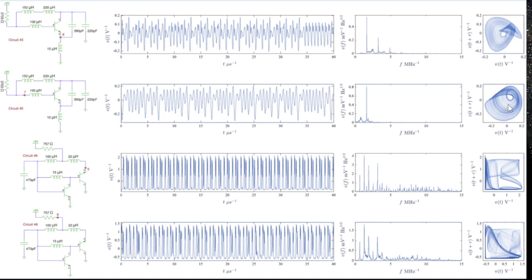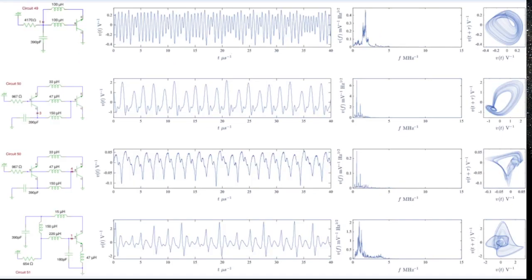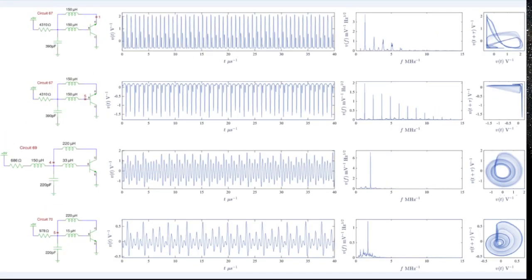But anyway, if you look over on the right at that second picture, you can see the variation between the big loop and the small loop. And all that stuff in between is like what we saw as we were adjusting a value in that feedback, and it was oscillating back and forth. Now, what they're showing here in that second diagram with the spikes, I don't know if it's a Fourier transform, but it's more like the harmonics. It's telling you what frequencies are being generated in this noise. You can see the scale, it's going from 0 to 15 megahertz. This is all megahertz in all of these.